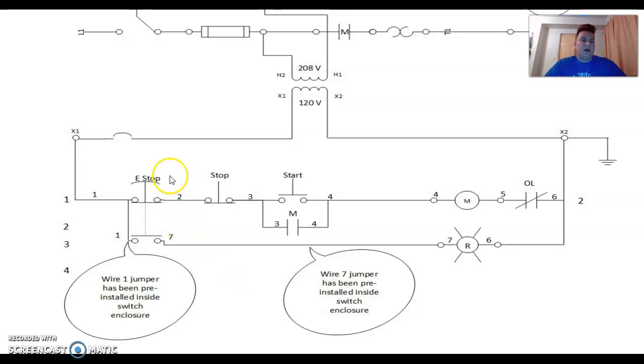Here I wanted to show this shop job again because I do like the usage of the e-stop. It is something that we're going to try and get a little bit more familiar with next semester when we use the conveyor system and things like that. E-stops are obviously very important in control circuits and in control situations. They need to be able to turn off the entire process with one human motion. So here we have the e-stop that's basically in series with the start-stop station, and that's just basic 3-wire control. You could talk about how the e-stop is in there to kill the circuit all at once.